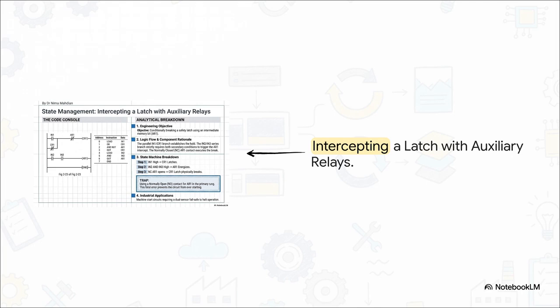And this diagram brilliantly illustrates that solution. Walk with me through this 3-step state machine on the ladder diagram. On the very top rung, that parallel IN1 and CR1 branch is what establishes the hold. When IN1 goes high, CR1 turns on. And because CR1 is wired in parallel with IN1, even when you let go of that start button, CR1 keeps itself latched on.